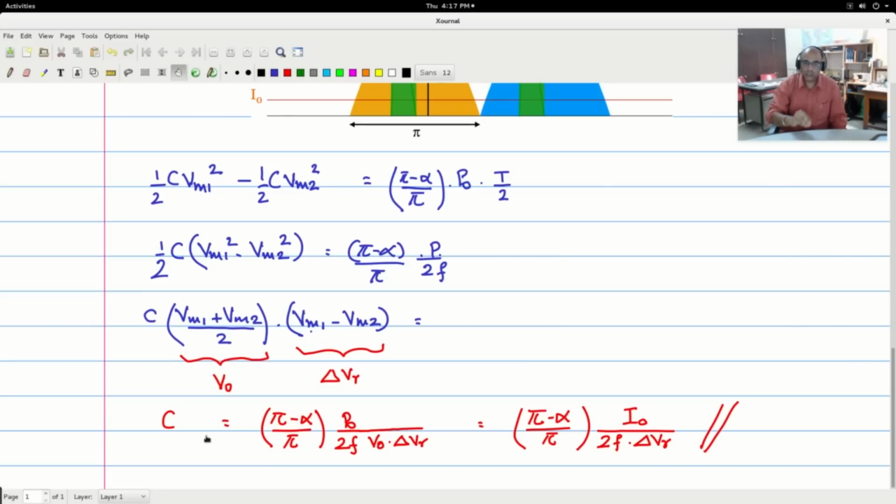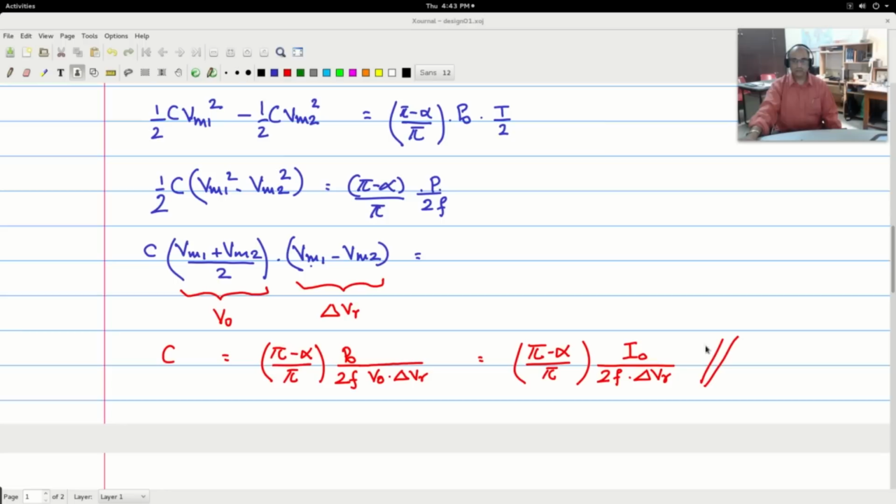So normally what is done in practice is, once you calculate, let us say you get some 10 or 15 microfarads, you will take 3 times that value, so 30 microfarads, and put that value. So that even if the capacitor that you have bought is minus 40% down, it will be able to handle these kinds of variations. So this is how you calculate the value of C.